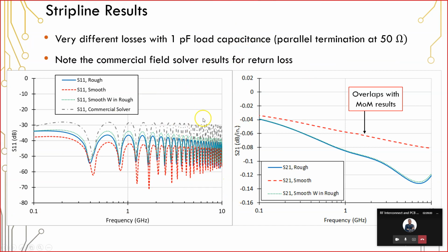First thing that we see, on the left, we have some S parameter data here from 0.1 to 10 gigahertz. So here in this mid-range portion of the right side of the graph, this is the region you would be operating in if you were dealing with an ISM band or Wi-Fi or Bluetooth. So these curves are still actually very good. Now, the S11 S parameter tells you how much power is reflected. So this is a measure of reflected power.